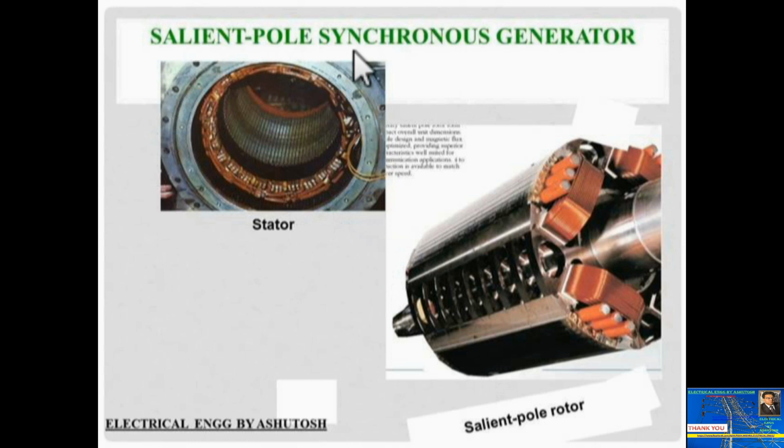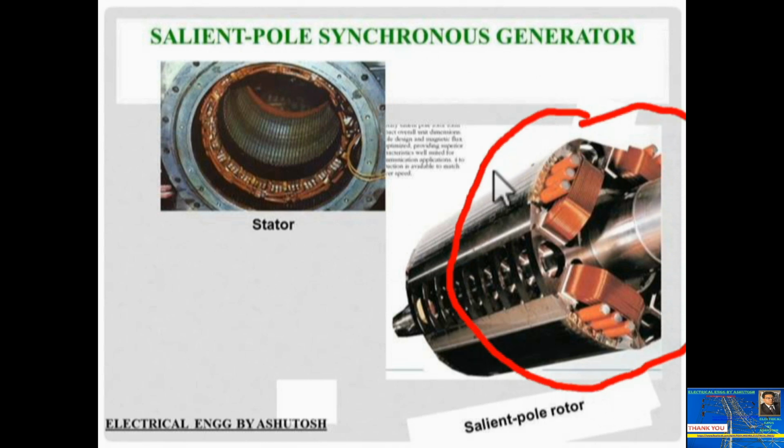This is a salient pole synchronous generator, and this is the salient pole rotor. This part is the projected poles, and these are the field coils, the field windings.